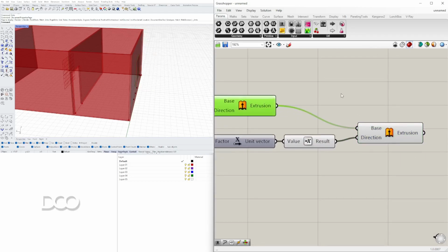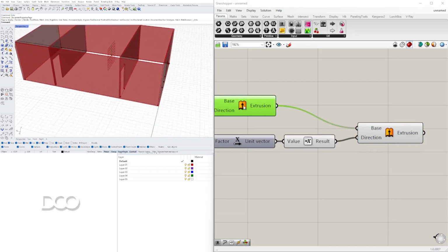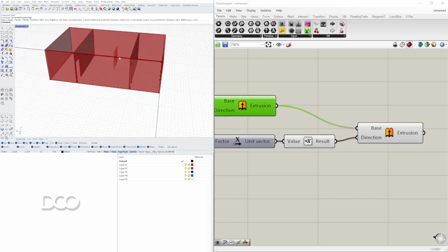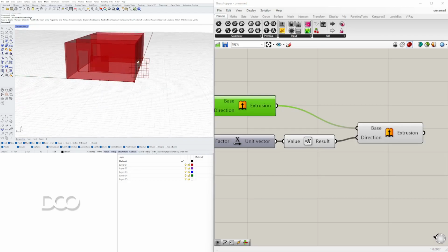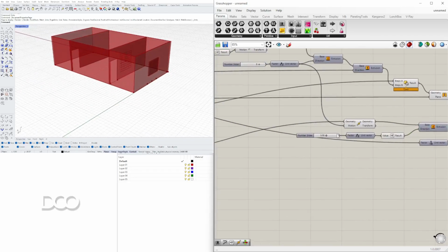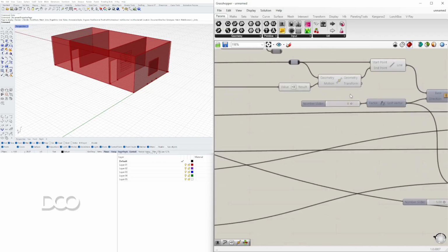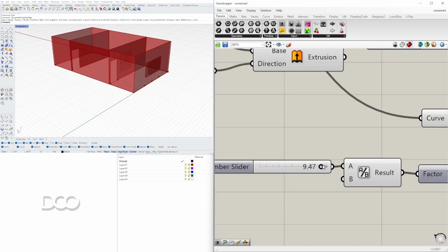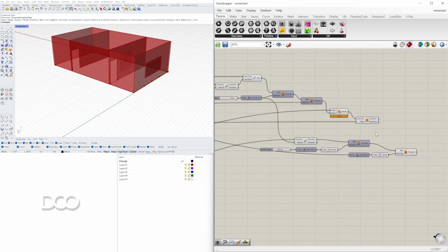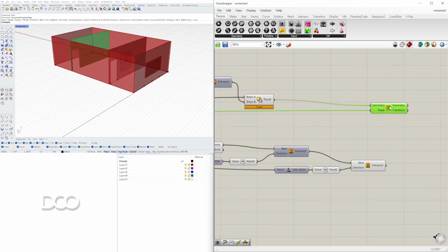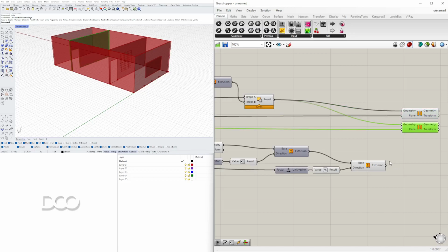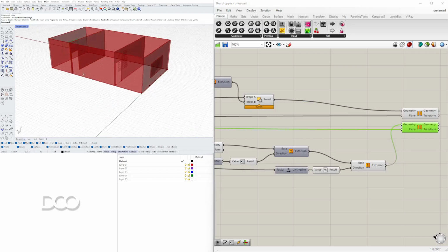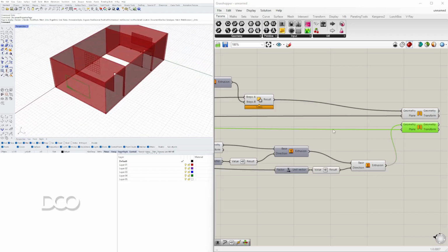Now I can plug in the overall size, so disable the preview to prevent everything overlapping. And I can use the same mirror plane to mirror it to the other side, and then we'll subtract it from the overall size here. What we need to do is take this, make a copy, slide it down, tap Alt to make a copy, or Control C, Control V. Now we'll plug the geometry into the same input, since it has the same plane.